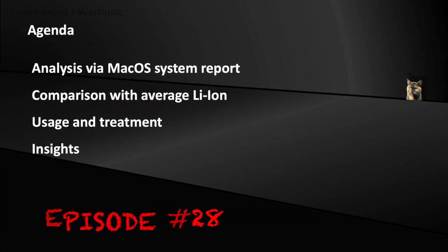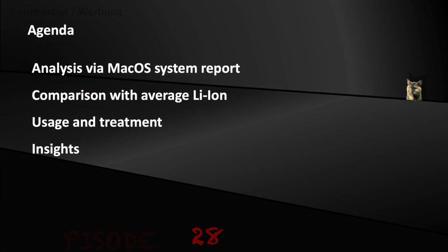In this video, I will show how to analyze a MacBook battery using the system reports and how to interpret the results. I will demonstrate this with my 9-year-old MacBook Air. However, the method is universal and can be applied to any computer accordingly. In order to judge whether the results are good or bad, I will compare the results with an average lithium-ion battery's degradation.